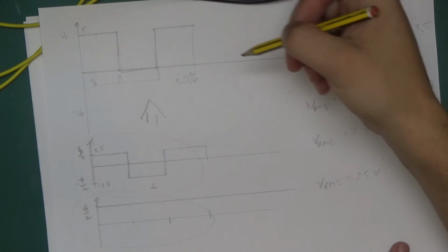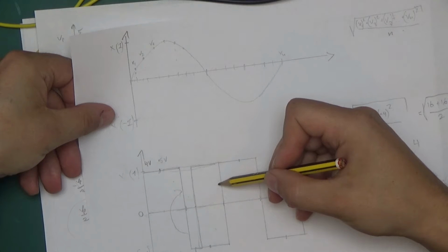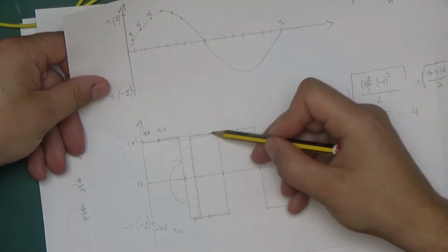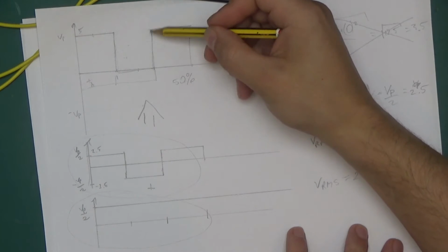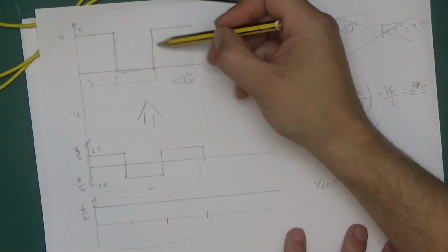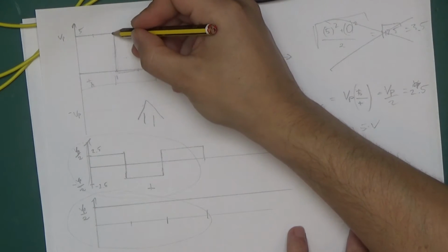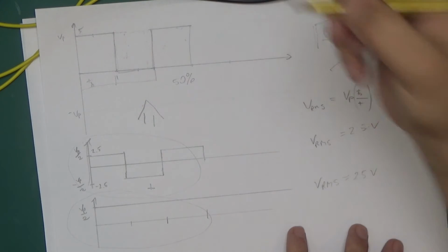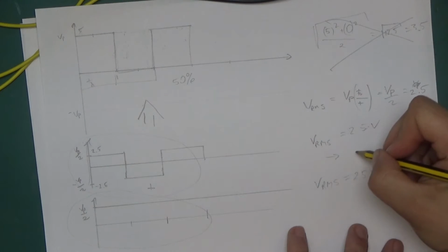The duty cycle determines the RMS value of the signal, and that wasn't the case with a symmetrical waveform, because if we flip it over, then it all evens out and it becomes a DC value. With a positive square wave, where it goes to 0 volts and back, there's nothing to flip over, so the actual duty cycle makes a lot of difference. And if you think about it, the closer this duty cycle comes to being almost a DC value, the RMS value would tend towards Vp.